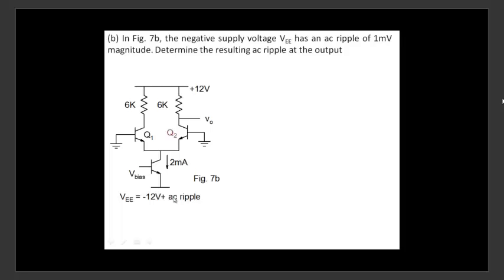And I have to find out, now look at this: is this AC ripple differential mode or is it common mode? Look at the two halves. Differential or common? Is it present for only one half, not present for the other half, present for the left half and not present for the right half? It's common. Now, one of the properties of a differential pair is what? All the common mode part is usually rejected, is attenuated. So this ripple is a common mode signal.